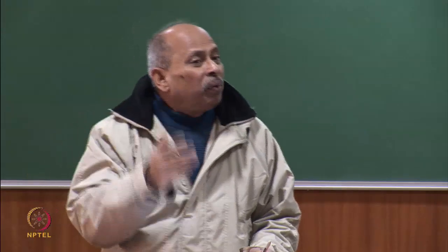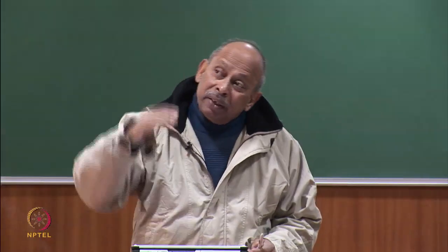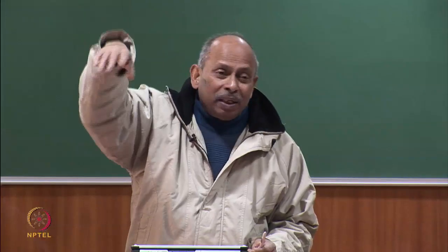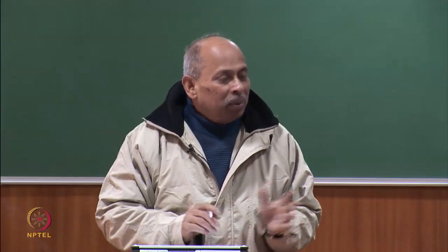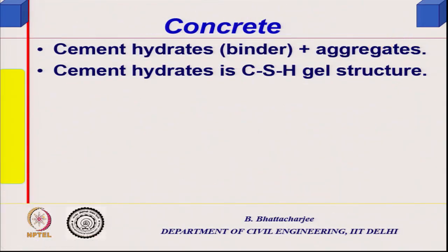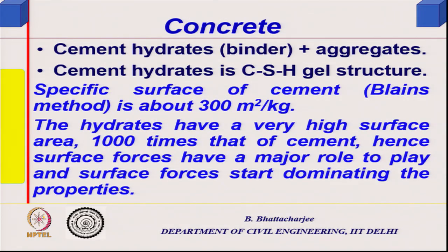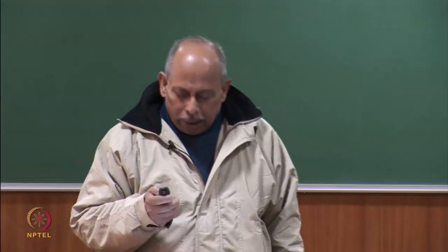So in a post-fire building, if the concrete structure has reached 800 degrees centigrade, you scratch it, everything will simply come out. So that's the behavior of concrete. Concrete under fire, that's how it behaves, right? So we'll just quickly look into this after I respond to some of your questions. A little bit of concrete we'll look into, right?